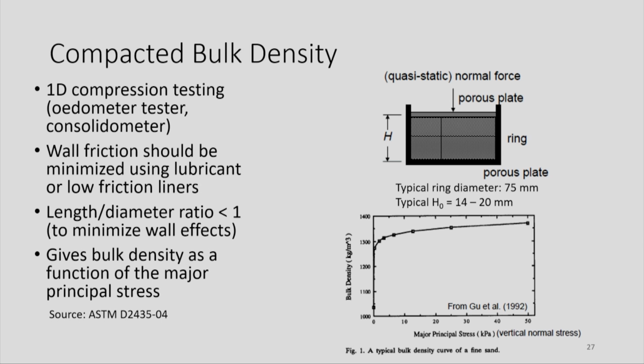Okay. And generally for powders, a typical 70 or 75 mm ring diameter is common to get the compacts or compact densities. Again, it can vary too, but these are common sizes for powders. One of the challenges, again, will be wall friction, right, when you're compacting.